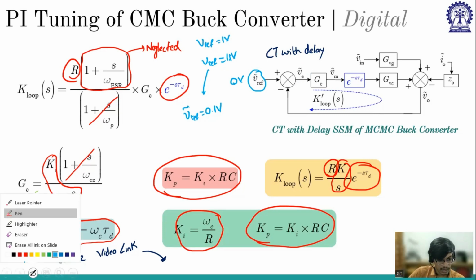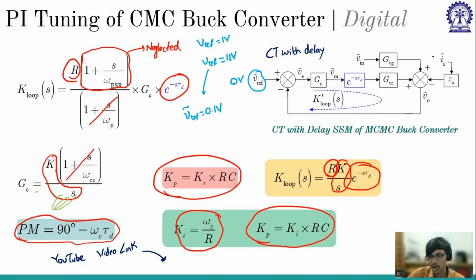And in the other case, where we talk about load transient, say I0 is 1 ampere and the new I0 dash is 5 amperes. So my I0 perturb is how much? 4 amperes. So my I0 perturb becomes 4 amperes into Z0. It is again negative. So there will be this V0 perturb. What will happen? It will fall, right? We have discussed that when there is a load step up, V0 will fall.